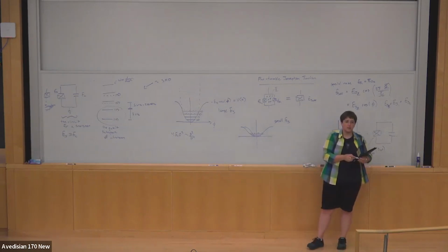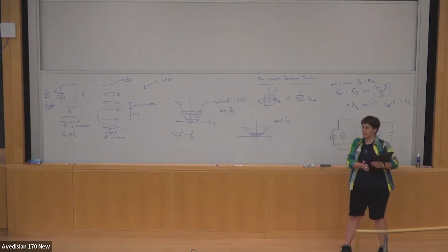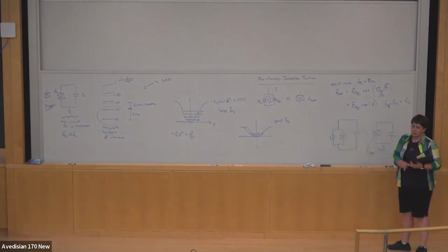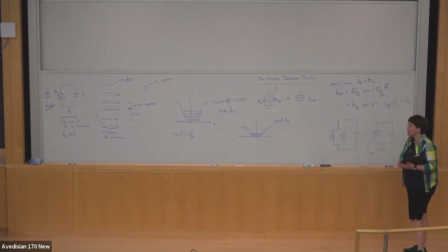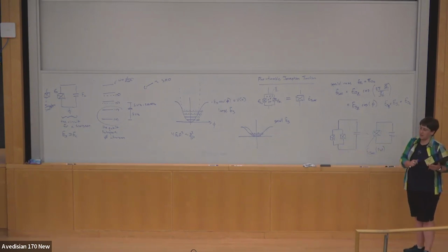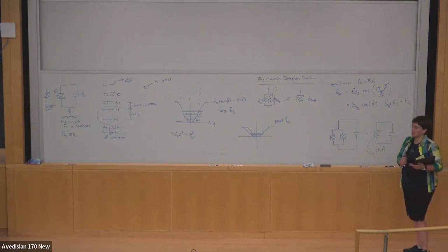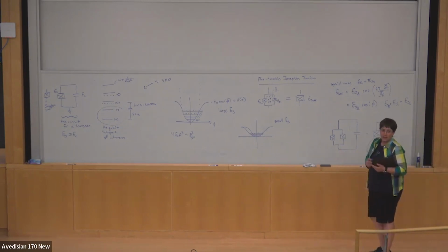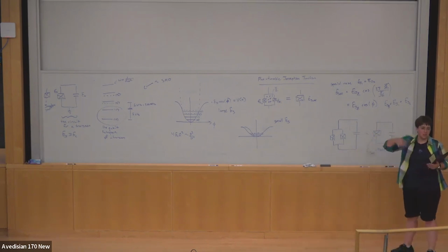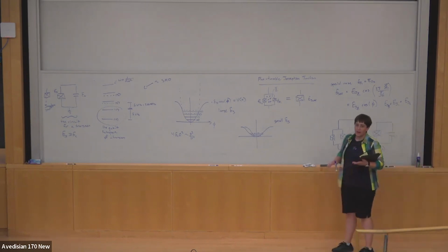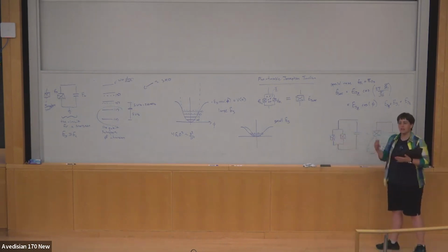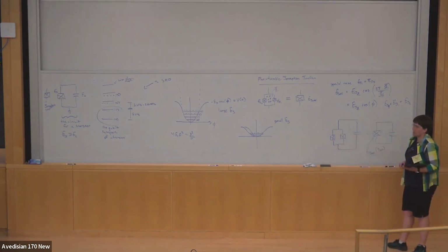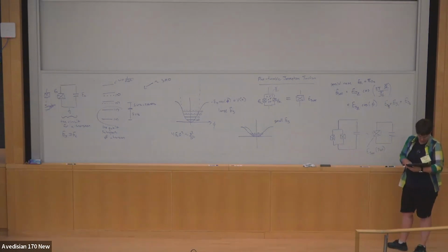And so there's a very nice way that you can tune the frequency of this thing. In my lab, we're a little bit nuts, and so we routinely tune these things between about 3 gigahertz and 10 gigahertz, depending on which particular shenanigans we're up to on any given day. So you have a lot of frequency tunability with the oscillator, and this is a very standard trick people use either to make things degenerate, say to run a gate, or turn things on and off, adjust amplitudes and stuff like that.